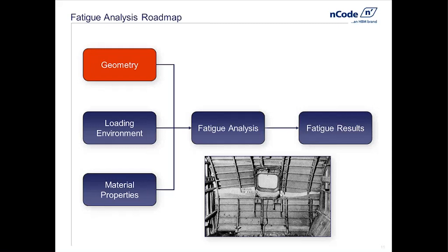A number of these de Havilland Comets actually failed in a completely catastrophic manner. There was very little understanding of redundant load paths at the time, or of the need for load and structural redundancy. So the problem was that this window was actually quite square, which led to a high stress concentration in its corner. Also, this is a jet aircraft, so for the first time it could fly very high, but to do so it needed to be pressurized for occupant safety.